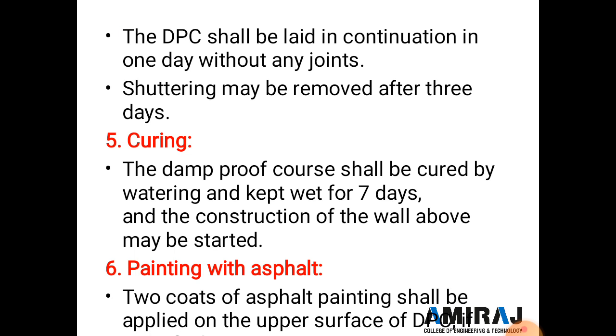Now the next specification is curing. So the damp proof course shall be cured by water for 7 days, and the construction of the wall above may be started after the 7 days.